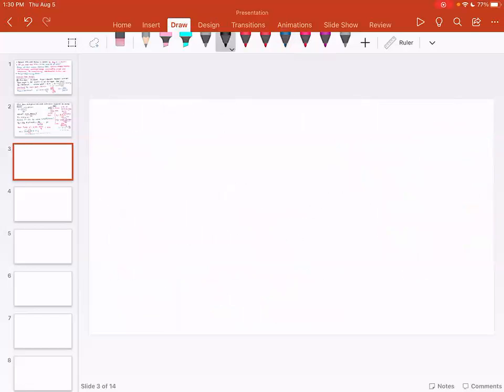So I will make a note. CV is equal to 350 divided by 350 plus V, where this velocity has to be in meters per second. But when I use the equation Vp is equal to pi times d times n by 60, I replace d n by number of teeth, 24, multiplied by module.